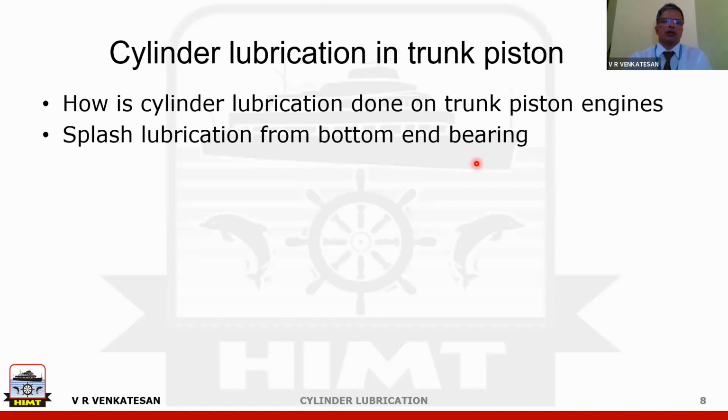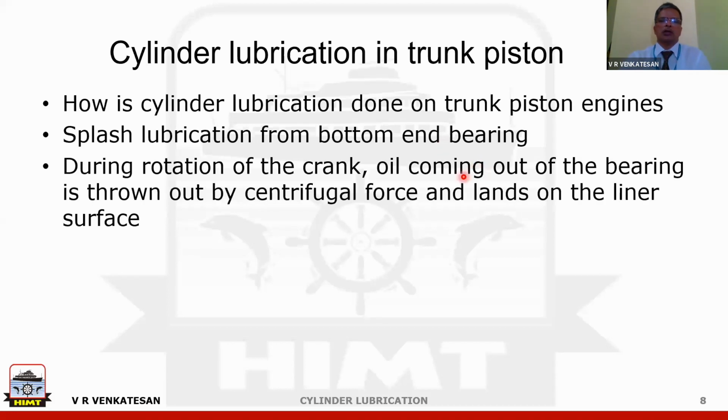Whenever your priming lube oil pump is running, if you go and open the crankcase and see, you will see oil coming out of all the bearings. But imagine when the engine is running, the same oil coming out of the bearing will be thrown out by the centrifugal force.